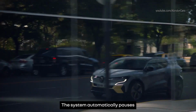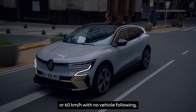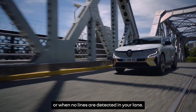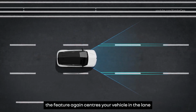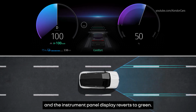The system automatically pauses when you're traveling at less than 37.2 miles per hour or 60 kilometers per hour with no vehicle following, or when your vehicle touches or crosses a line, or when no lines are detected in your lane. When the right conditions are present, the feature again centers your vehicle in the lane and the instrument panel display reverts to green.